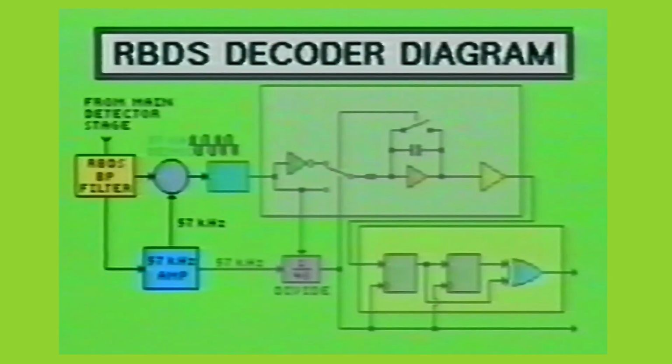A shaping filter, identical in function to the shaping filter contained in the previously mentioned encoder, is also used in the decoder. Ideally, both shaping filters share each half of the overall data channel spectrum shaping. This is done to improve signal-to-noise characteristics.